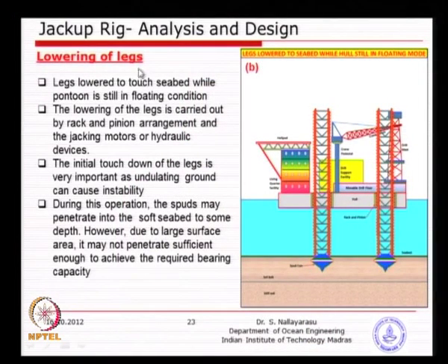So, as you try to lower the legs, you have seen the graphics. The sequence depends 100% on the mechanical device. Of course, to some extent you have to do this operation in controlled environmental conditions, because there could be horizontal loads at the time of lowering the legs, which can spoil the connection between the rack and pinion.